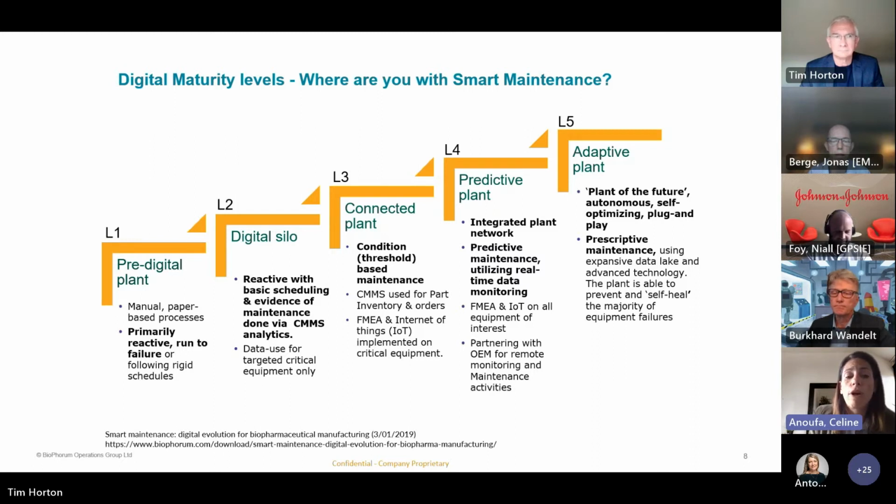So level 4 is all about predictive maintenance. That means connected to the cloud. The plan is to use real-time condition monitoring data, operational context of the production site, OEM global threshold recommendations, and maintenance logs to build algorithms so that we can predict equipment failure and therefore downtime. And for that activity, we believe with my colleague that the partnership between the pharmaceutical companies and OEMs and suppliers is essential to develop a data lake of information that will fill the predictive model and provide meaningful recommendations.